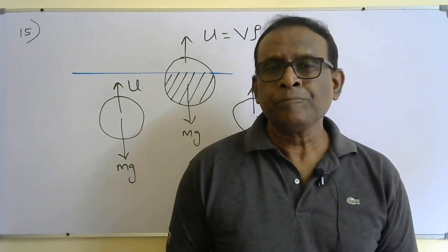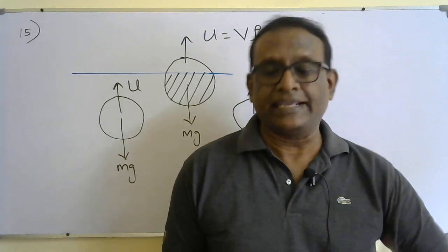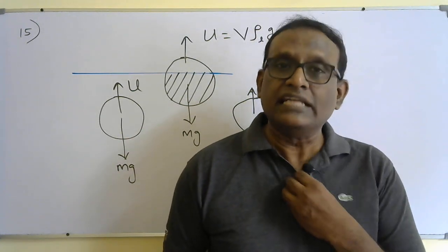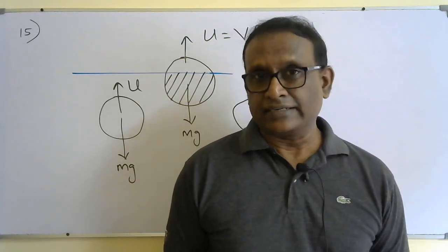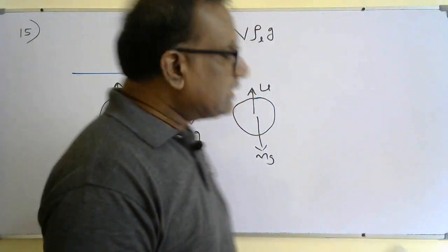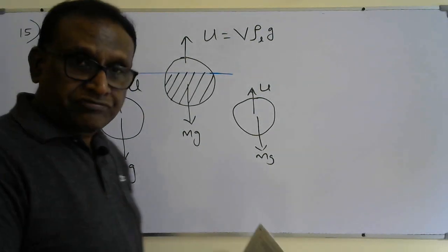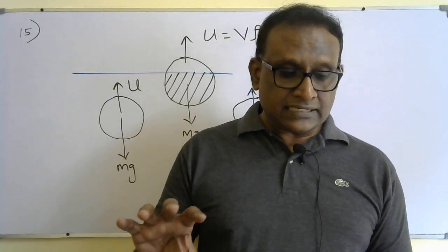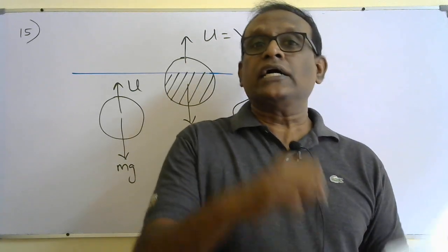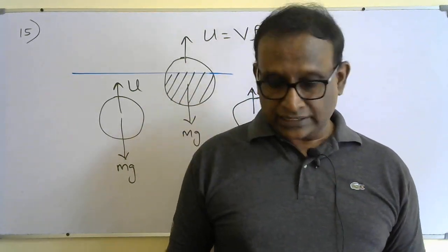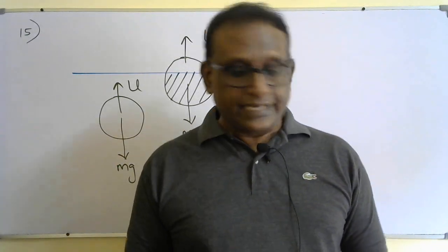So what happens here? When the temperature increases, the density of the liquid will decrease. When the density decreases, the upthrust will decrease. The total weight, including the bulb and the disc together, will be different for different sets of bulb and disc. Those marked with higher temperature have lower total weight. Lower total weight.